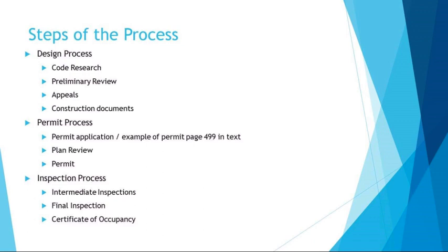Now, sometimes, as you've heard about if you read in the textbook, there may be a temporary certificate of occupancy. This is an example like I have everything in but the granite countertops. And so they'll do a temporary certificate of occupancy. This will allow the project or portion of the project to be occupied as long as the code official feels that the occupants will not be in any danger because the entire project is incomplete.